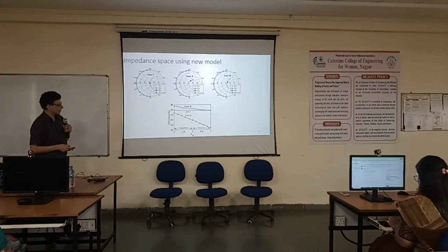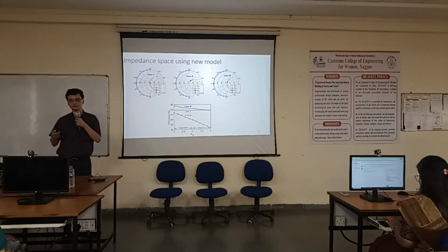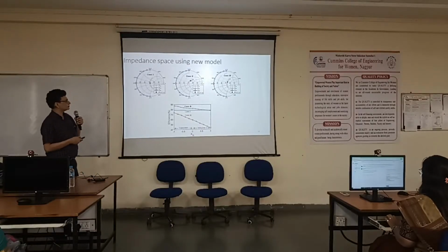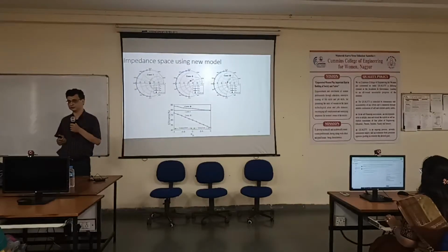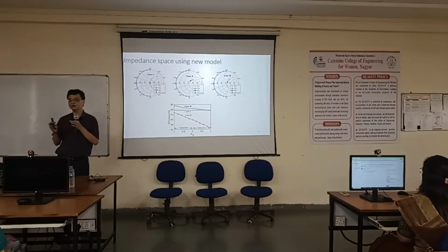Then if we calculate the efficiency for the various cases, we see that for the capacitive case, when we have a capacitive load, we get a higher efficiency. This phenomenon was observed, that when we have a capacitive second harmonic load, the efficiency is higher for the same magnitude. Right, in electrical engineering we see duality of everything.